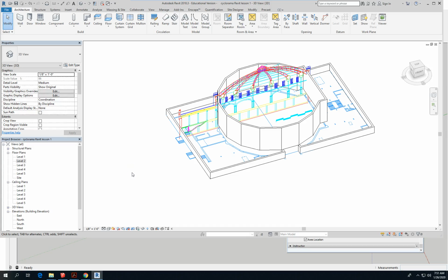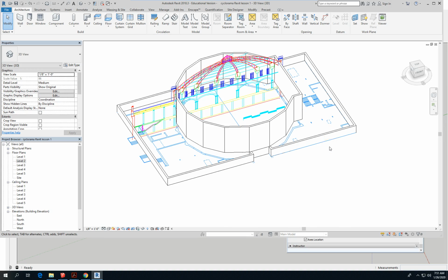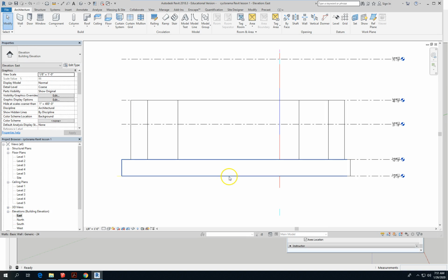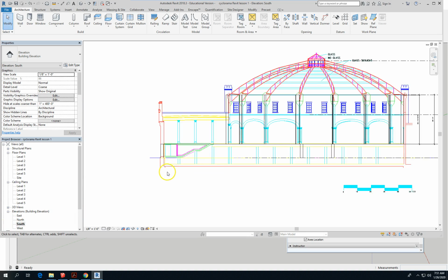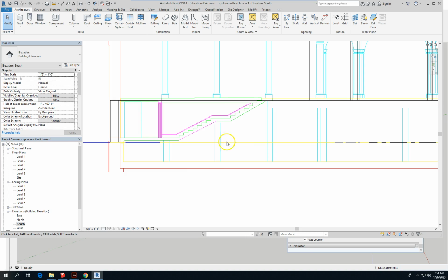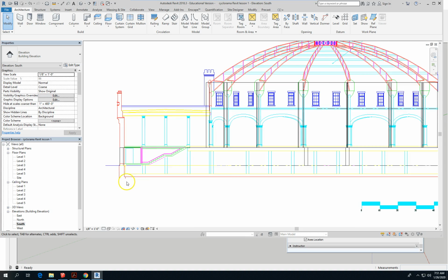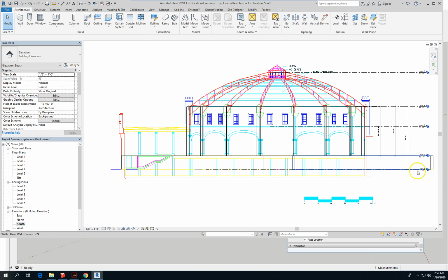This is lesson 2, cyclorama in Revit, and we'll do a little bit of work with floors and site topography. So we have walls, but we do not have any floor slabs or information modeled. And remember, 1 or 2 of these elevations are in wireframe mode, so let's talk about the strategy of the floor. I'm going to have level 1 be the ground plane, and we're not going to bother with the basement below it.